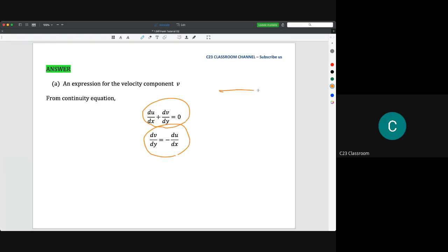As I said, if you have a pipe here, the velocity here, proportional to the perpendicular cross-sectional area, will give you a flow rate Q. But if you have V here, this V is not perpendicular to the cross-sectional area of that pipe, of that object. So you cannot simply say that the flow rate is equal to V times this area. It is totally wrong. That's why in this situation, we need to do this method to get the value of V.